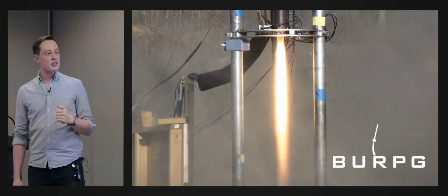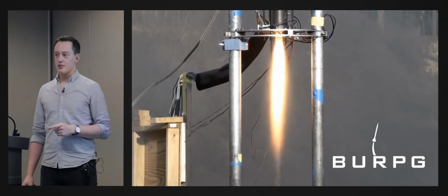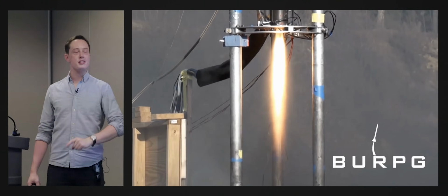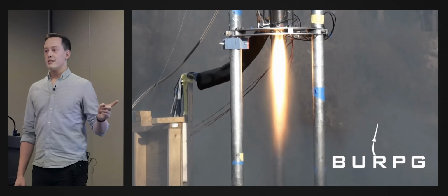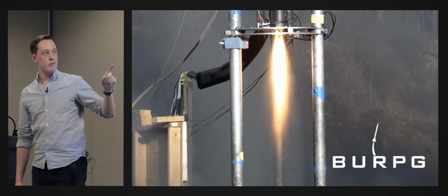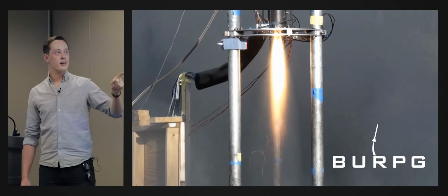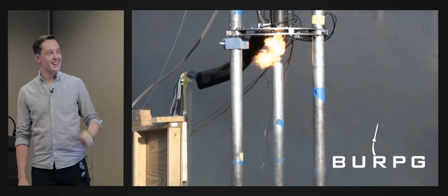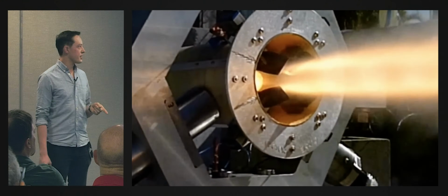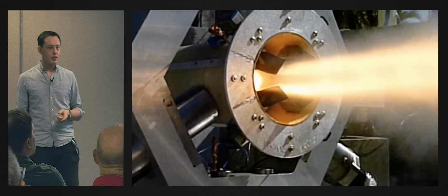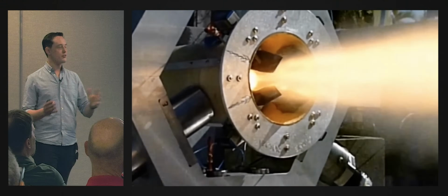The other approach you can use is called LITVC, and though the screen is cut off here, this is from the Boston University Rocket Propulsion Group. LITVC stands for Liquid Injection Thrust Vector Control. And by injecting a reactive or inert gas into the exhaust stream, you can change the direction of the thrust in a really binary way. Isn't that crazy? And then finally, this is the Vector Bravo system from Florida Tech, and this is a thrust paddle approach where you put small paddles into the exhaust stream in order to deflect the thrust.